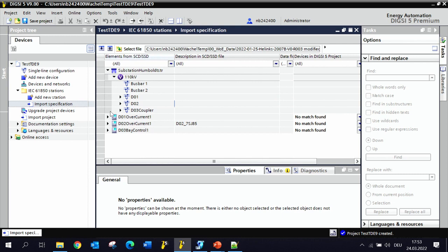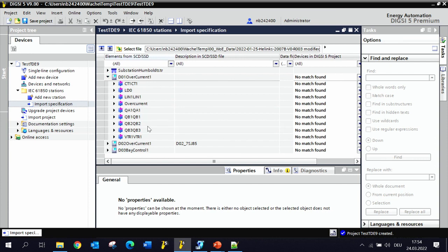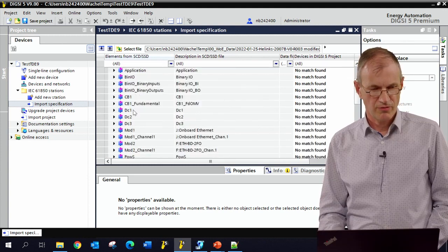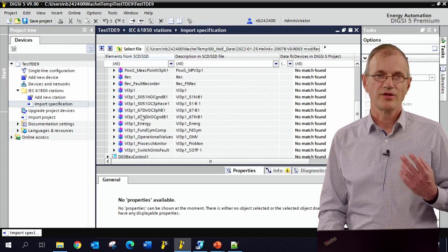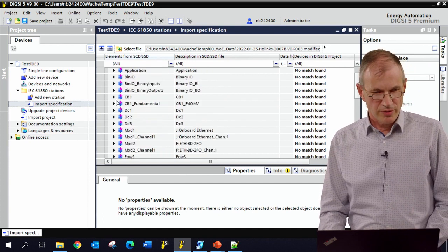Of course, for someone like us who has the task to now engineer the devices, the view of the IEDs here is much more comfortable. Here we have the 3 IEDs as a requirements list in this 61850 language. You see already the difference between the D01 and the D02 bay. In the D01, let's have a look. This is the device from the library, from the SCT tool. It looks different than the view here. This device is based on the Siemens ICD, and it uses our library and our description. So let's now